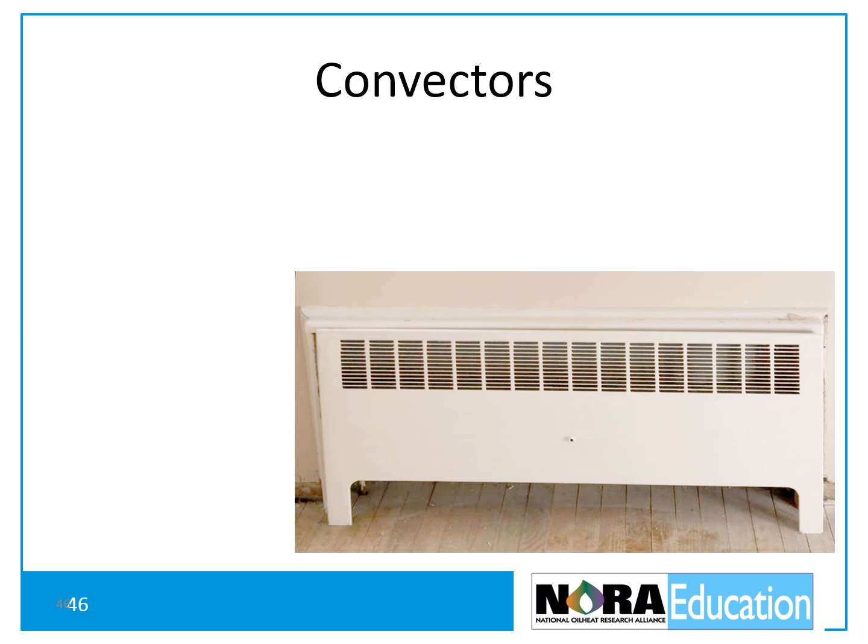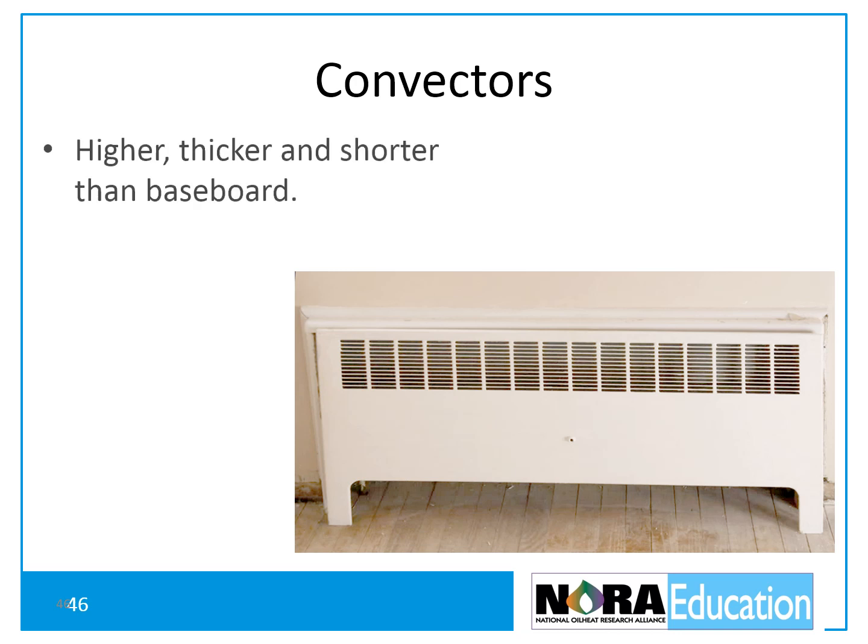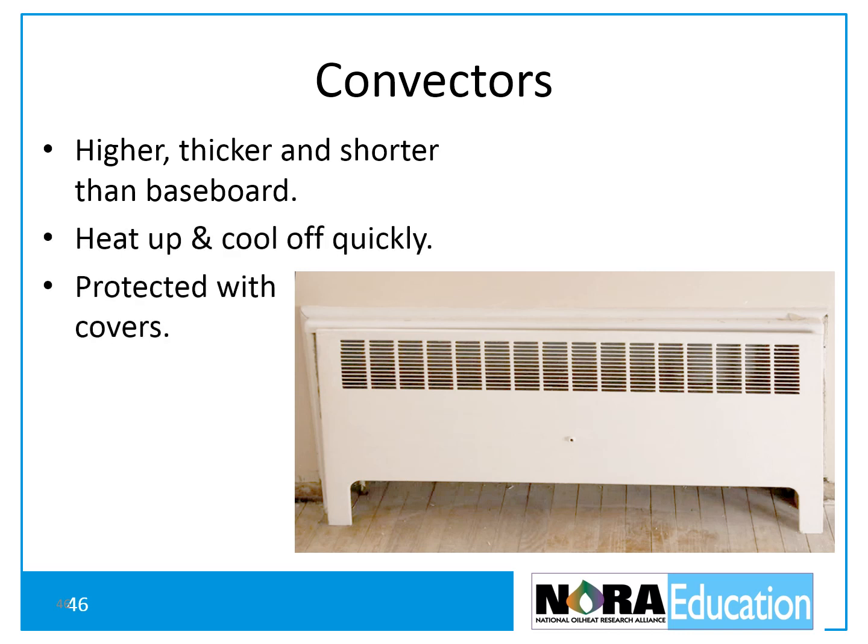Convectors are similar to fin tube baseboard, but they tend to be thicker, higher, and not as long. They heat up quickly and cool off quickly. Surface temperatures are not an issue as they are protected with covers, and like fin tube baseboard, they need enough room in front to create convective currents.